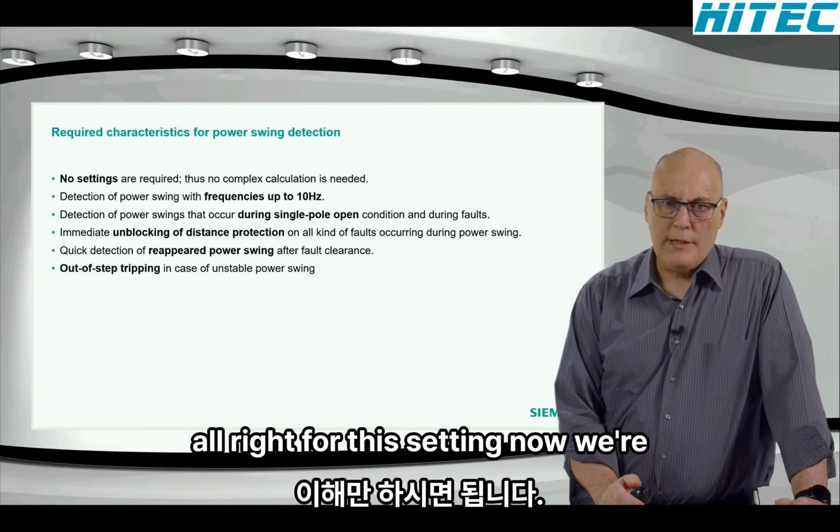Out-of-step protection in SIPROTEC 5 is a separate function, okay, that you would use. If you want to use out-of-step protection, it's the same principle behind it, but it's a different thing. It's not distance protection. It's a function that you apply to recover from, say, a disaster, one can call it. If the system has a real serious disaster, like cascading tripping, then you need to island the system. It's a separate concept, not a distance protection concept, and therefore it's a separate function, the out-of-step protection function in the SIPROTEC 5 relays.